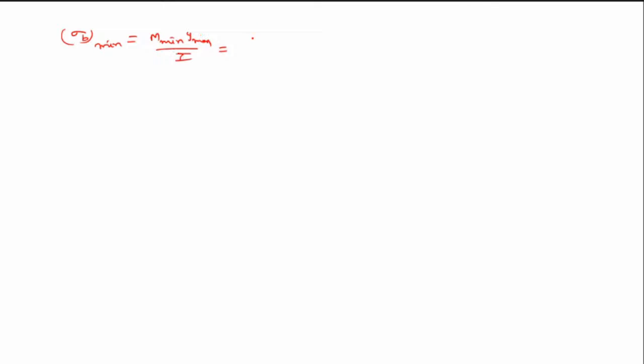That is nothing but M minimum is 80,000, Y max is 20 by 2, that is 10, and I is 12 into 20 cubed by 12. So this is around 100 Newton per mm square. So this is your minimum stress. Sorry, it is 100.